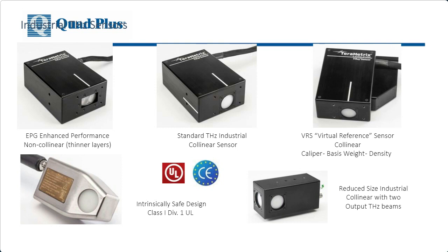The other kind of calibration is when you say, okay, I know how thick, I know what the time delay is between my two reflections, but what's the speed of light that's in between there? That can vary with material that's being used. And so that's more what Josh was talking about in comparing it maybe to laboratory measurements from the plant, where you can then just adjust the calibration that you're using so that you get the precise thickness.